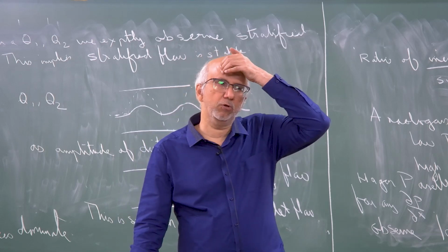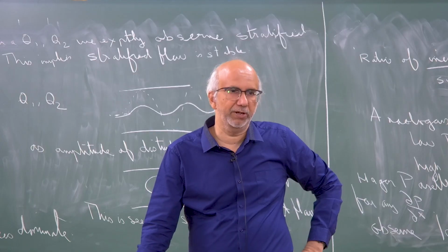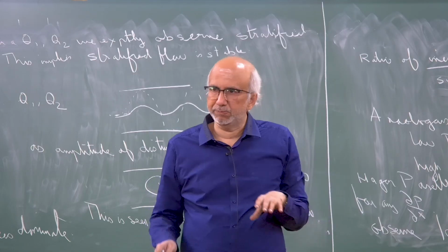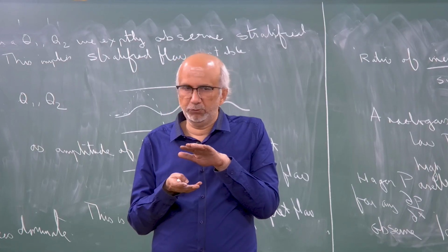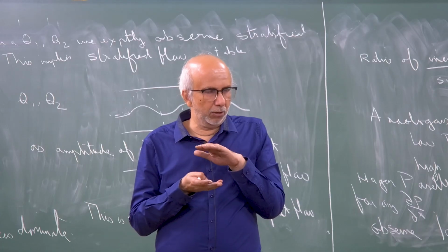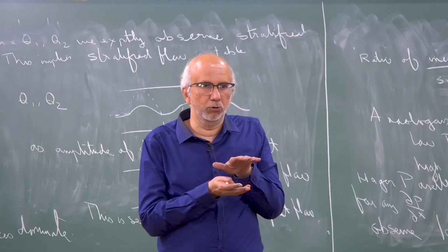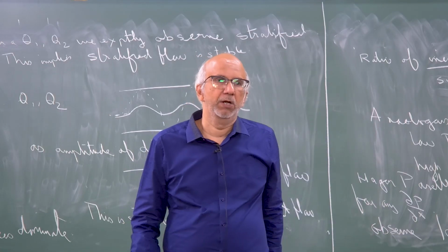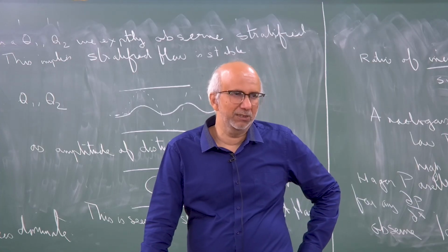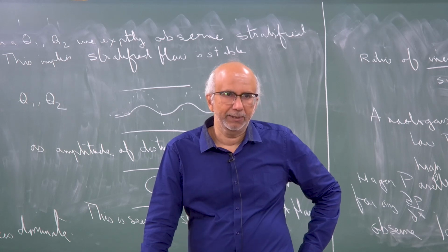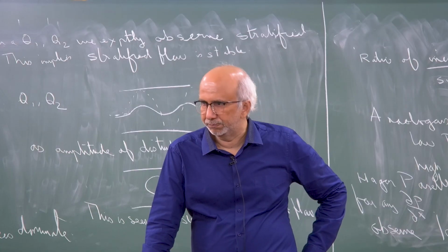If you remember, I told you that people have observed laminar flow up till Reynolds number 10 power 5 in the first class. That is because they did those experiments very carefully and tried to eliminate disturbances. So, if you can take a lot of pain and make sure that there are absolutely no disturbances to the flow, then you can push this limit of 2100 to a larger value. But typically that is not done, the disturbances will always be there, okay. And that is the reason we stop at 2100 and say 2100 is your transition.